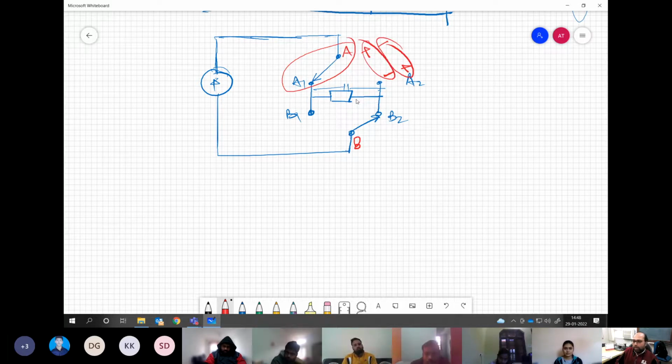Because we are talking about AC load over here, right? So the polarity of voltage could be anywhere, depending on whether you are putting the lagging load or leading load, what kind of load you are having there. So for any blocking voltage, this may be asked to block any polarity of voltage. This is not defined. The only meaning is to say this, that if you ask the polarity of this voltage between A and A2, this is not defined, which means we should be prepared for both polarity of voltages.